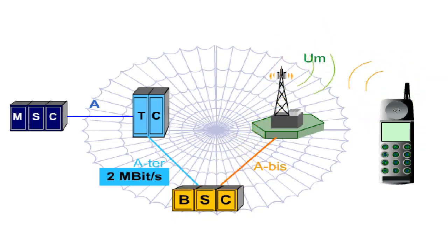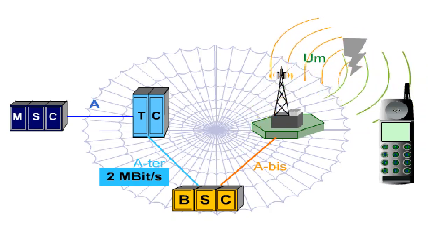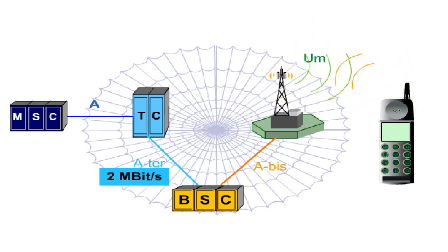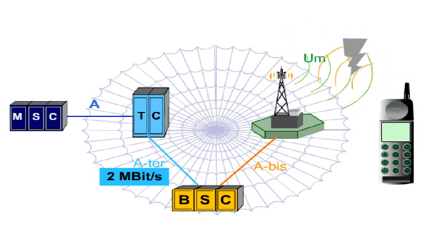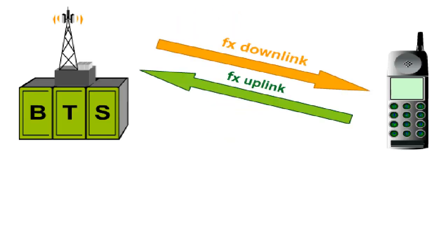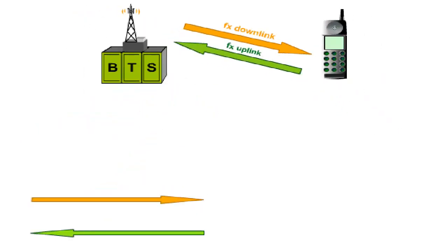The air interface, or UM, is the weakest part of a radio link. In GSM, a lot is done to ensure high quality, security and reliability. At the air interface, the frequencies are arranged in pairs. Each uplink frequency has a downlink frequency permanently assigned to it. The uplink signal goes from the mobile station to the base station, and the downlink signal goes in the opposite direction, from the base station to the mobile. The arrangement in pairs is what actually enables simultaneous communication.